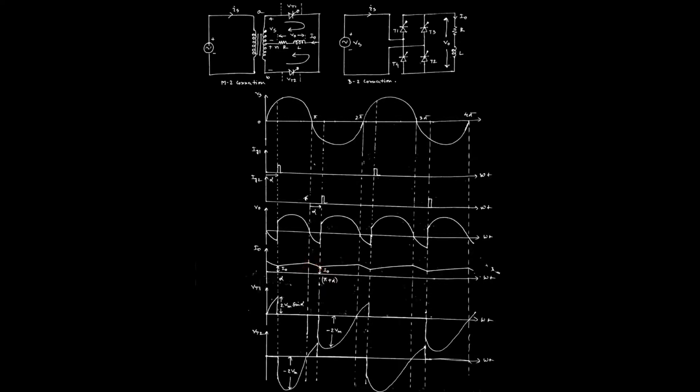That is why the inductor current gradually decreases from its higher value to the initial lower value, that is I0. In a similar way, when the thyristor T2 starts conducting, again the inductor starts storing energy, and the circuit current starts increasing from its initial I0 value to a particular value, and again starts discharging. In this way, it will be repeated from the next cycle onward.